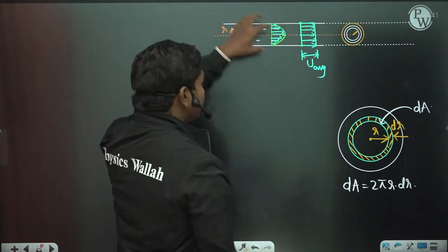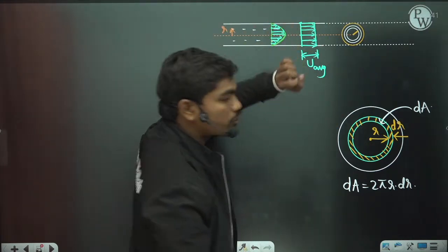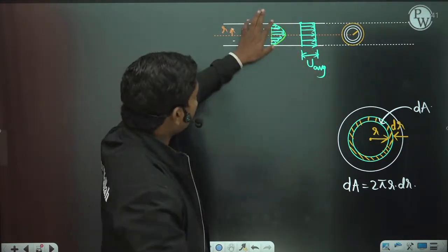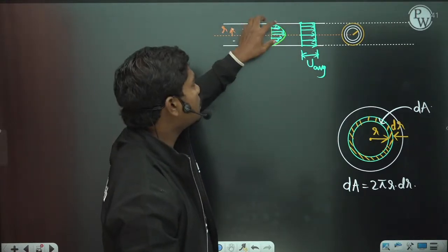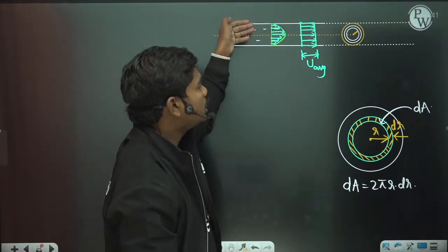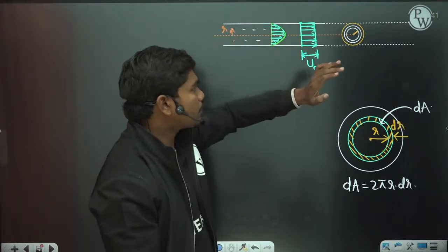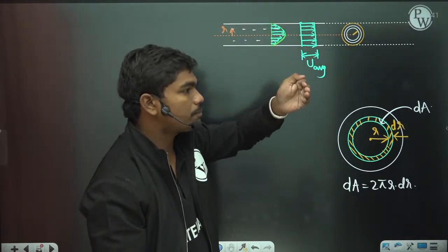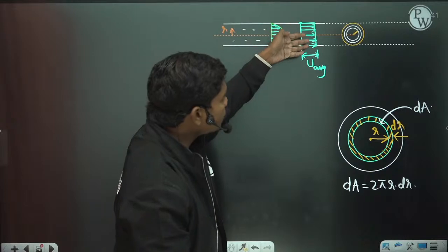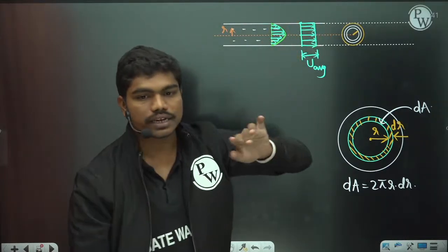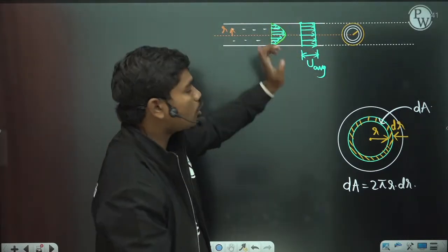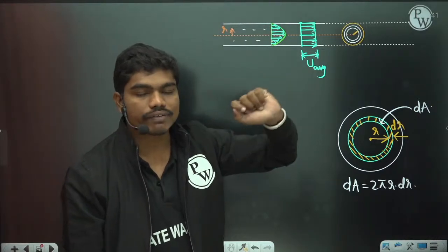for the same cross section you have the same amount of discharge. Try to understand here. Normally, because of this velocity profile, through this pipe of radius capital R, you have some discharge. Now, let us suppose for the same area of cross section of the pipe, the same pi r square, if u average is the velocity at any section, then the discharge should be the same as in the original case. Clear? So that's how we define the average velocity.